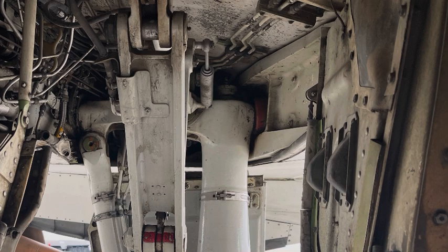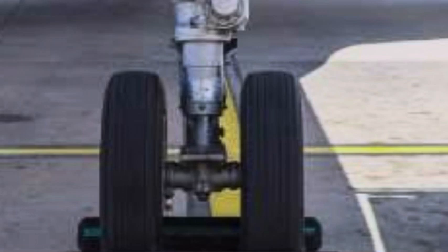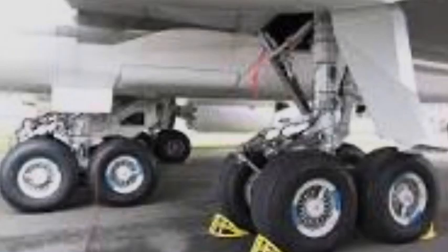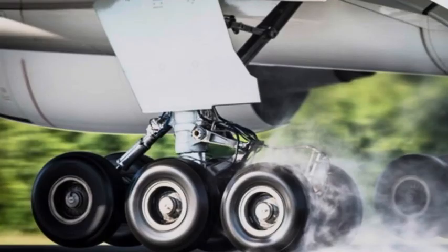Besides, the landing gear should have a mechanism to absorb this shock without bringing any damage or deformation to its own linkages. Regarding the number of wheels attached to the landing gear, it differs from one aircraft model to another. Mostly in medium body aircraft, we have conventional two-wheel landing gears, mainly the main landing gears, left and right. But as the fuselage extends and becomes larger, more wheels are required on the landing gear, mainly the main landing gears, because we need the force to be distributed between the wheels, and more wheels will support the weight of the aircraft.